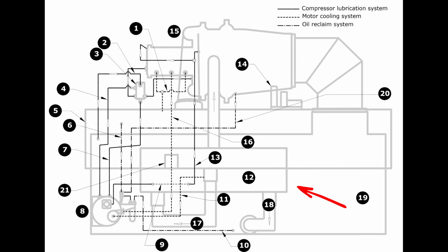Set them to delta pressure? I'm not familiar with doing it via delta pressure across them because typically we don't have a pressure tap necessarily to set it here. We do it based off of either a predetermined flow, or, like the Dunham Bush one, you do it based off of the sight glass.